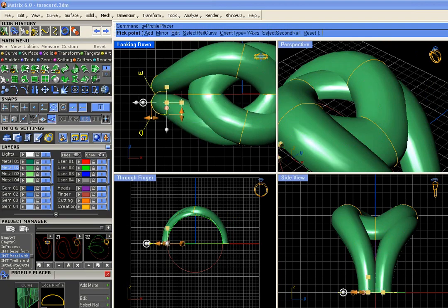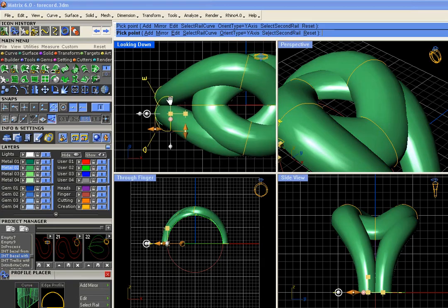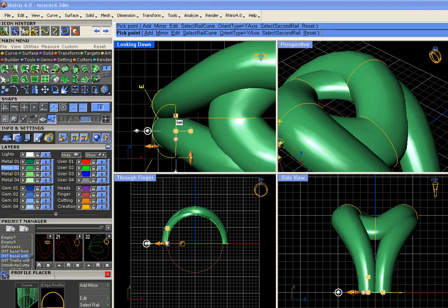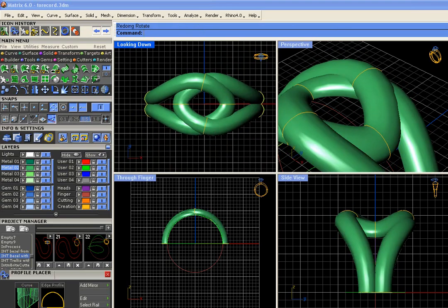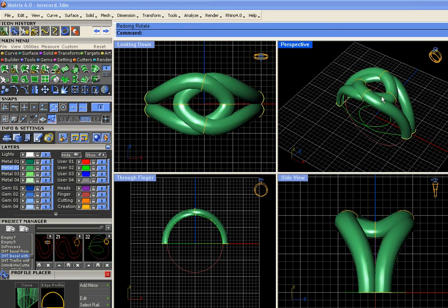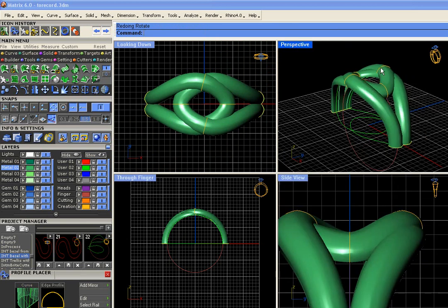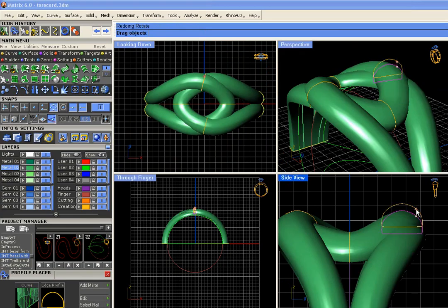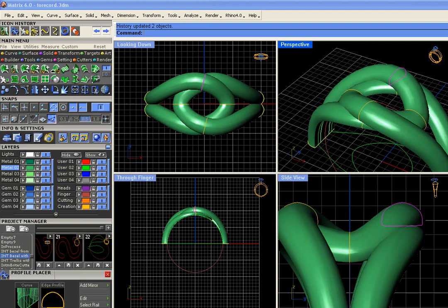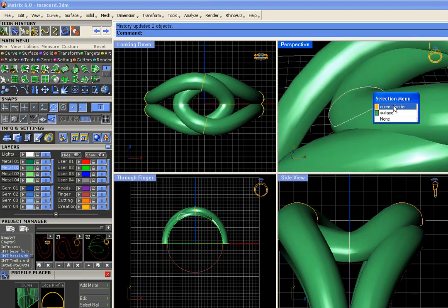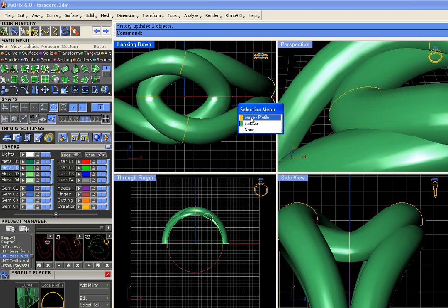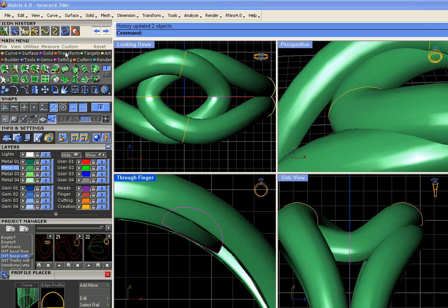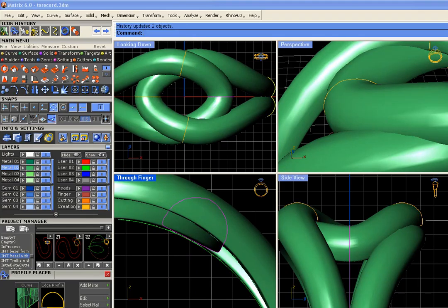F6. Like I said, I usually end up undoing all my changes and really liking the original one better. Incidentally, you can also just click and drag these around. Matrix history still updates, or if you like to scale them the old way with the scale tools, that's perfectly fine. Just make sure you remember which side's the original side, especially for Rhino history, so you don't break the history in Rhino. Matrix history doesn't care. So we can scale this using the old-fashioned way.